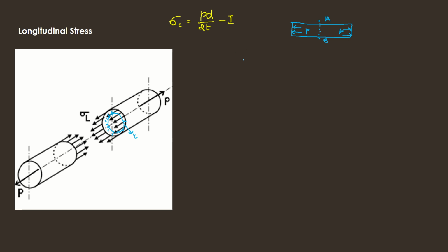Right. So here also we have to see when the failure occurs. When will the bursting happen? If the longitudinal force developed by the internal fluid pressure dominates the internal resistance offered by the metal, then the failure occurs. Right? So let us see now. Bursting force is equal to the resisting force. Bursting force, let us see.